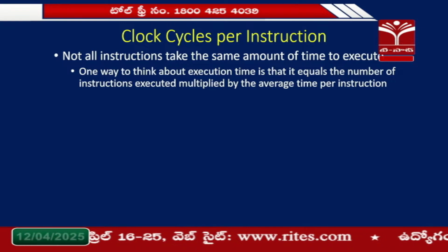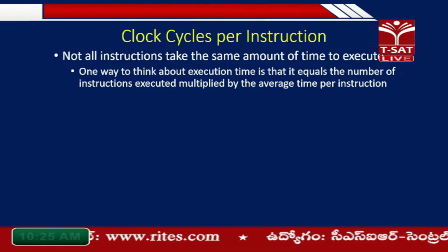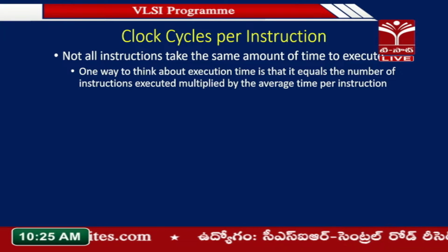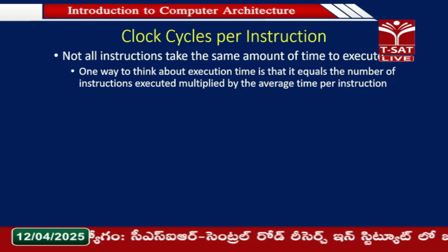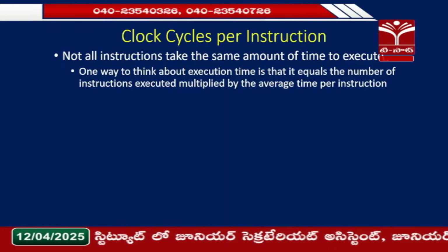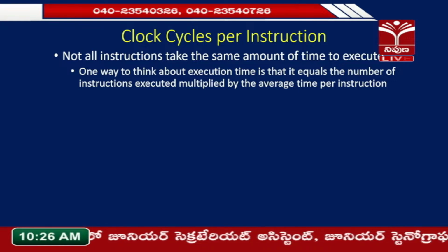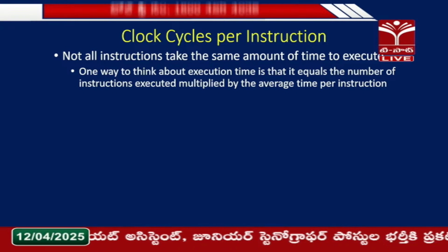Let us say you take an instruction like an adder, you can do it in 1 cycle, but a multiplier takes 2 cycles, because multiplication is a little bit algorithmically tougher problem to do. So, the CPU is taking 2 cycles as an example, but in any given program you have 100 add instructions, but you only have 50 multiply instructions, then you take an average of those.